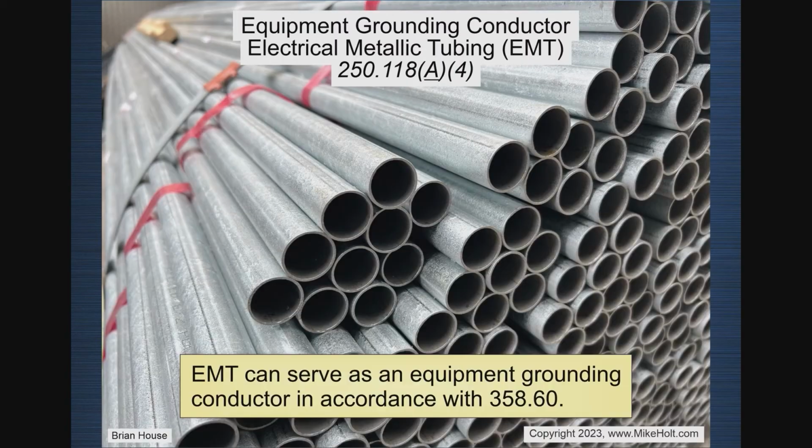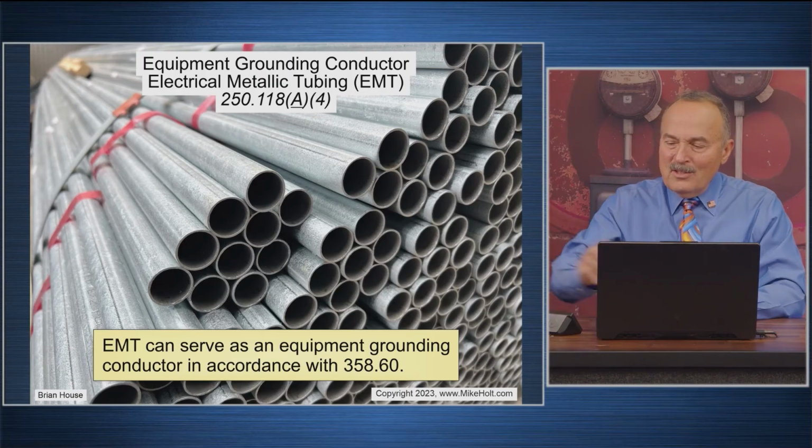It's interesting. It's so funny to watch social media. I'll show a picture of the box and it has EMT connected in there. Where's the ground wire in the pipe? And I'm like, any real electrician would always put a bond wire in the pipe. And I'm always sitting like, what the heck do I do with this guy? What do I say? You know what I mean?